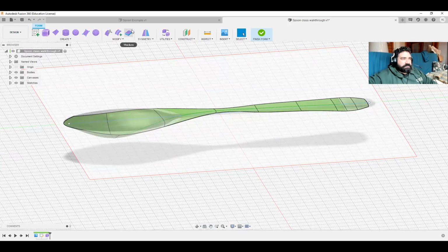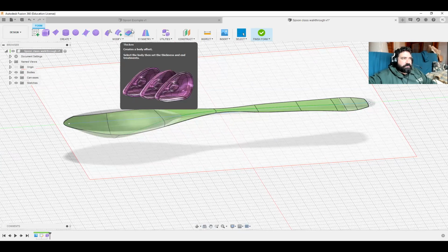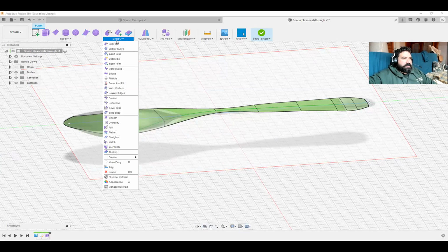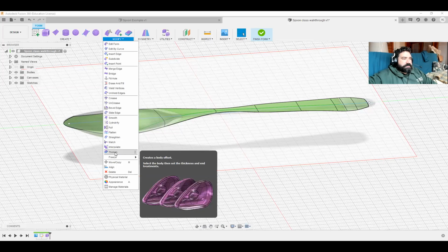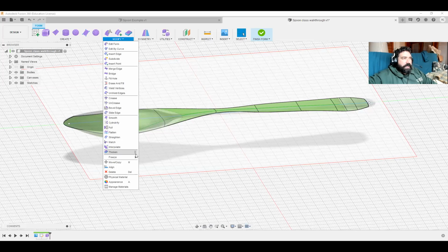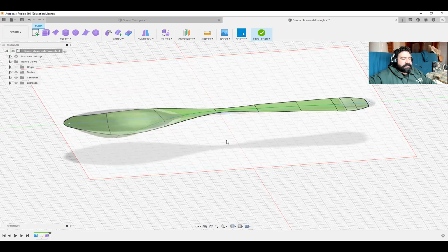What that is, literally, it thickens what you're working with. That's under the modifier. Down here, Thicken. I added that to my toolbar by mousing over the 3 dots to toolbar. You can also add it to your shortcuts, because remember, if you can't find something, press S as in September, brings up your shortcut bar. Now it's there. Or if you couldn't find it before, start typing in Thicken. Brings it up. Hooray. Select this whole thing.